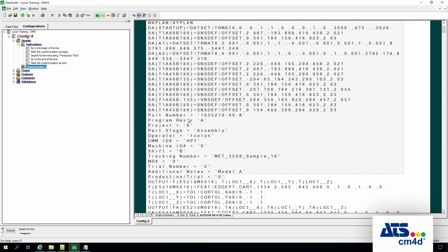So typically the routine would be something provided within the file that identifies the part name. So if you notice here where it says part number, we have a code here. So for this company, when they measure this particular collection of checks for a part or a sheet metal object, that part is identified with this code. So that's what we want to use as the routine name or routine label. So if we want to pick that up, what we can do is right click on characteristics, choose new characteristic, and within here it will create a new characteristic for us.